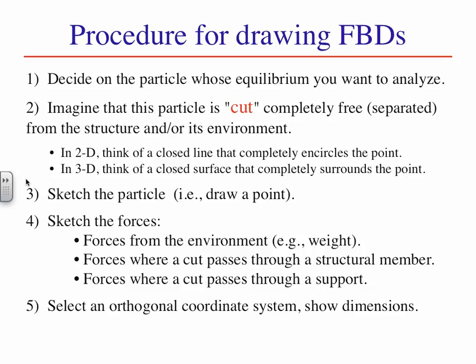Third, we put a point on the page to represent the particle. And then fourth, we identify and sketch all the forces acting on the particle, including those that develop in the process of isolating the particle from its surroundings. The latter include internal forces, where the isolating cut passes through a member of the assembly, or support reactions, where the cut passes through a point of anchorage.